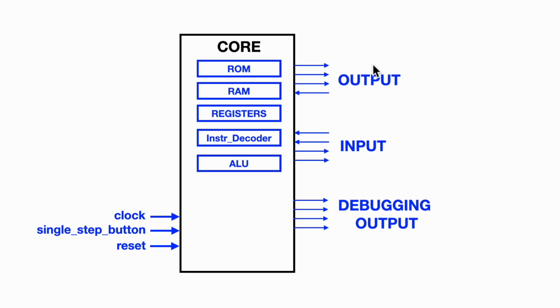So when we execute an out instruction, we have these 4 channels that will be active, and will basically send data from the core, more precisely from the accumulator register, to one of the I/O registers. And when we execute an in instruction, we will be asking for data from one of the peripheral devices, and we'll of course be storing that into the A register,